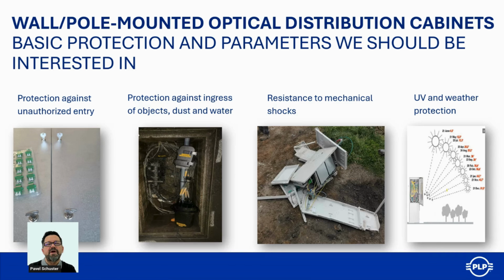For example, in a location where there is too much humidity or it's close to the seaside and so on, we also use higher rated enclosures or boxes with IP65 or 66. Then, for example, IP67 is already water resistant. It means we can keep it 1 meter under the water level for 1 minute. And IP68, which is the highest rating of the IP coverage, must be defined. It's, for example, say 5 meters under the water for 5 hours.